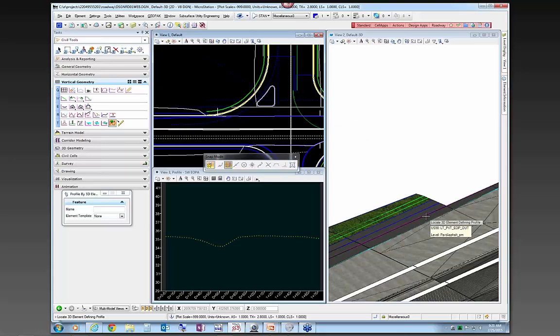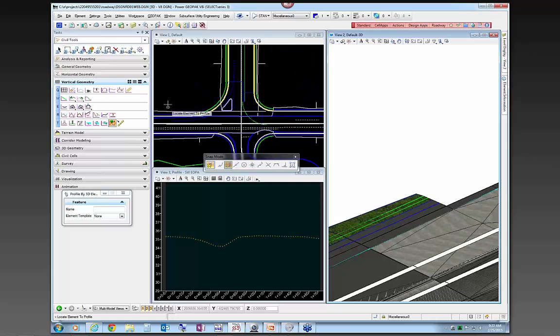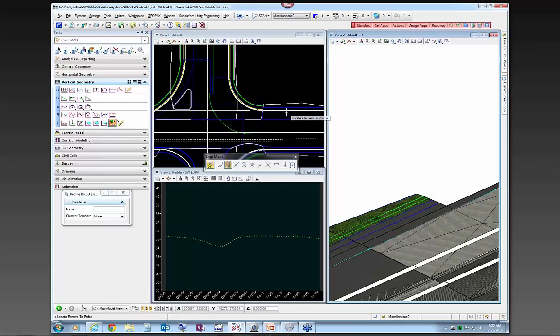And what I'm going to do is hover over this until I see the pavement asphalt PM line in the model that represents that particular 2D line, or where that is located in the model. And then when I click on it, it will actually apply this profile to that line, okay? Because these lines are just 2D right now. But in order to construct some 3Ds, we need to actually put profiles on them.